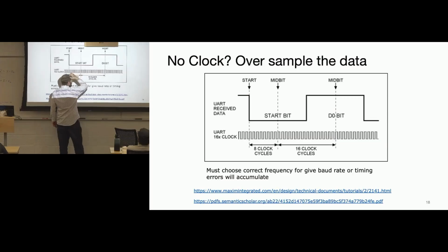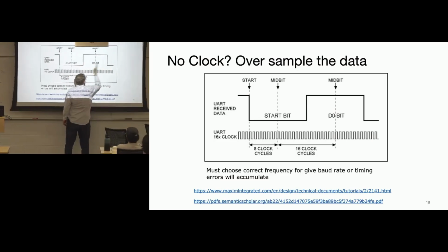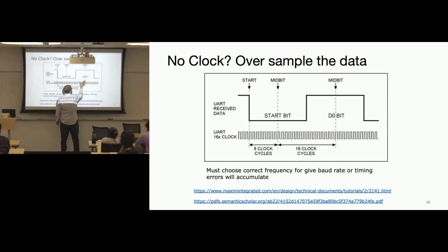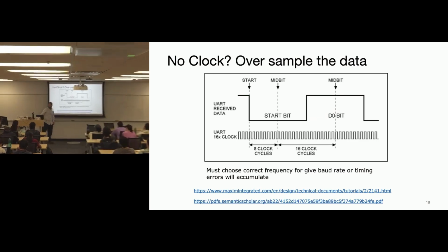Gotcha. What you want in almost all clocking strategies is for the data to be stable for a period of time. There's a little bit of skew here that we're not showing. So we want it to settle for a while, maybe a quarter of the bit width, or the period, from here to here. It needs to be stable for a while so that I know it's clockable.